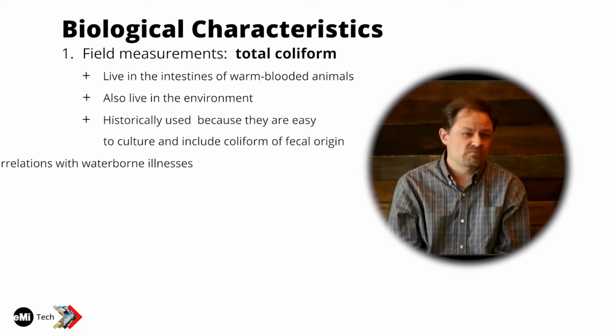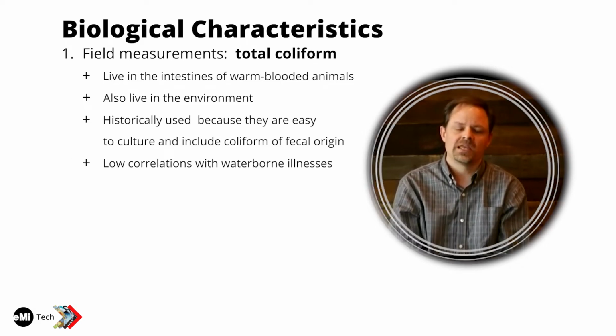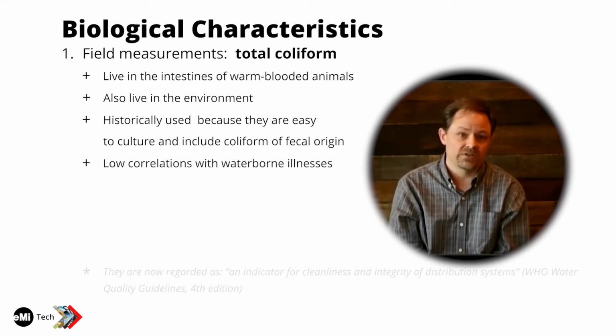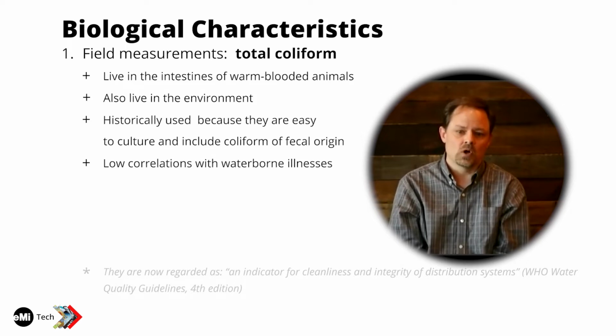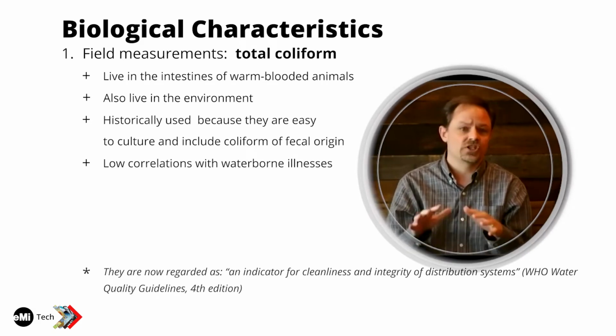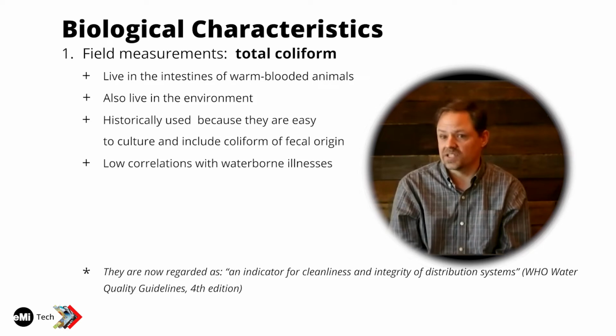But in the past 10, 20 years, there's been increasing research that actually shows that total coliform has a very low correlation with the occurrence of waterborne illnesses. So just because there's coliform in the water doesn't necessarily mean there's pathogens in the water. And as a result, total coliform are really viewed now more as an indication of just the general cleanliness of the water and the integrity of the system.